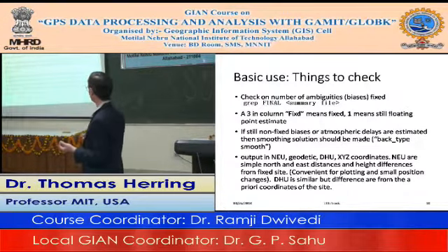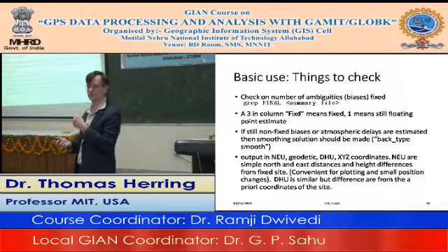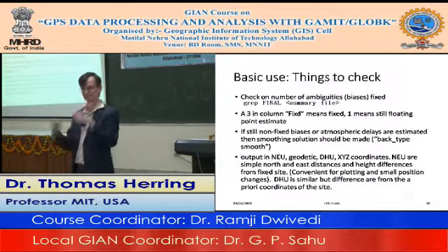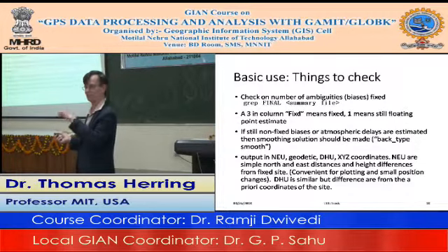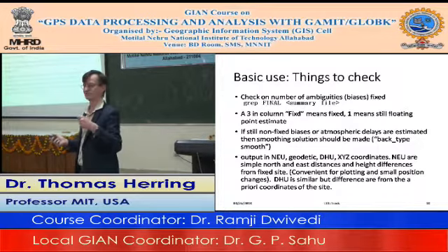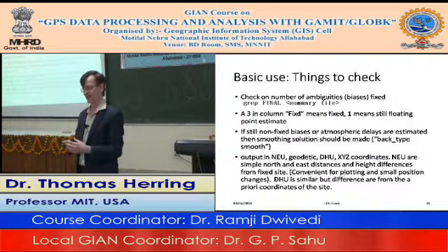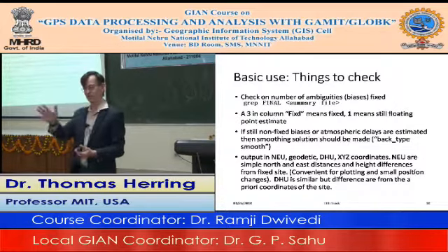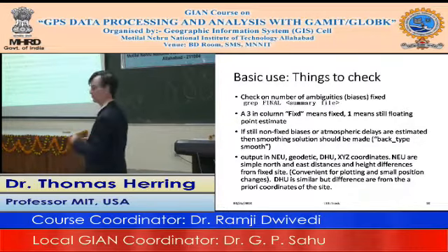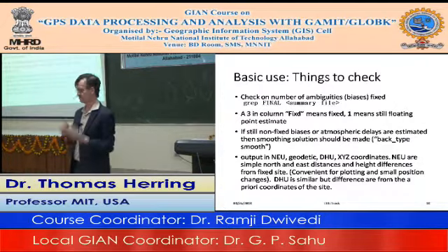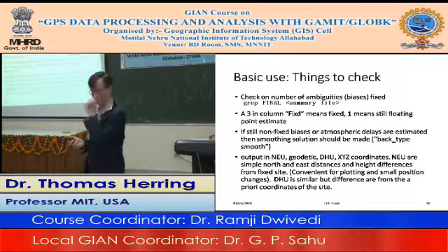You can also output in geodetic latitude, longitude, and ellipsoidal height. That's really good when you're doing aircraft. You can take those files, and we have a shell script that allows you to convert them to KML, and then you can show them in Google Earth. So if you've done an aircraft flight, you can show the trajectory plotted onto Google Earth, which is sometimes useful. Or if you've done a building survey, for example, you can display it back on Google Earth. Hopefully your Google Earth registration is good.